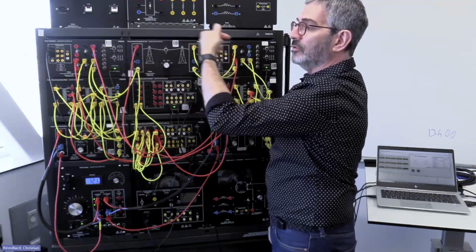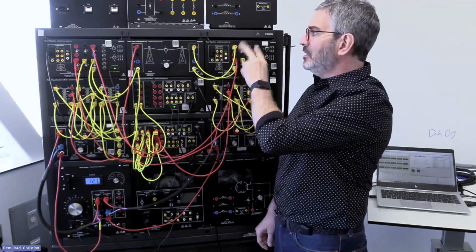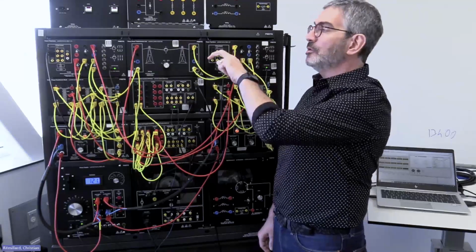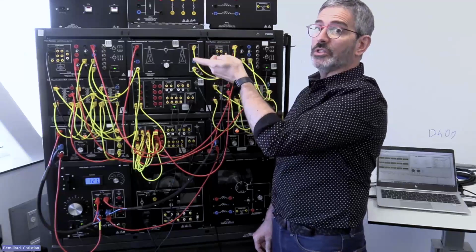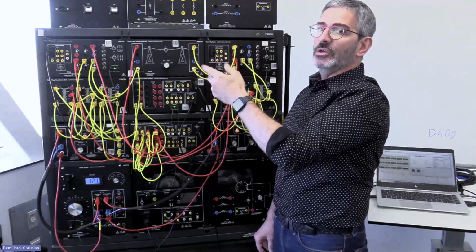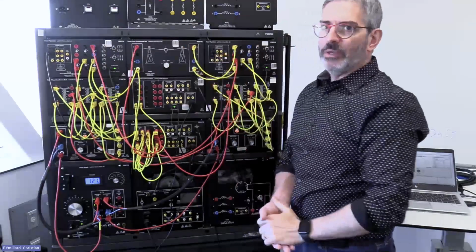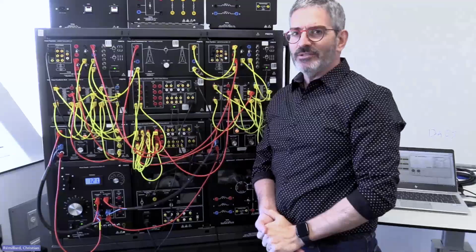So the flow of current is always in this direction, but then with the firing angle on our bridges, we can change the polarity of the voltage. So the voltage will be positive or negative, and based on the polarity of these voltages, we will have power flowing this way or power flowing the other way. All of that is explained, of course, in the exercise.